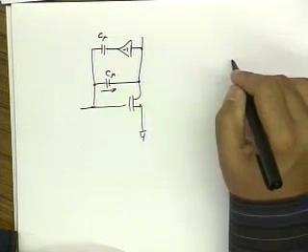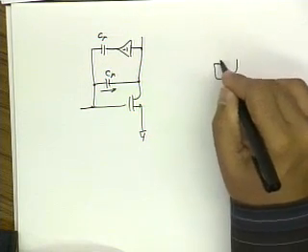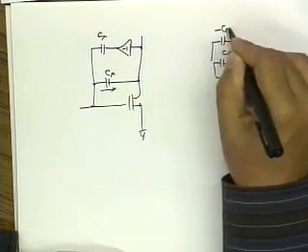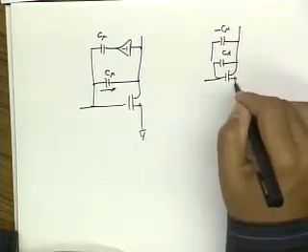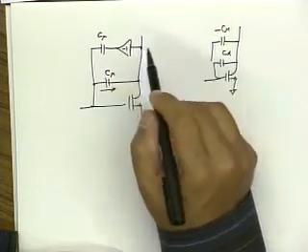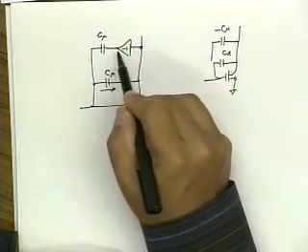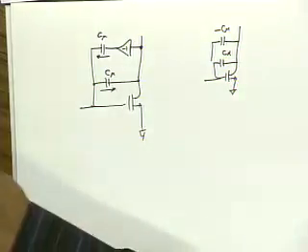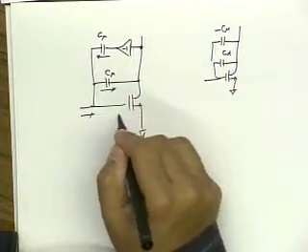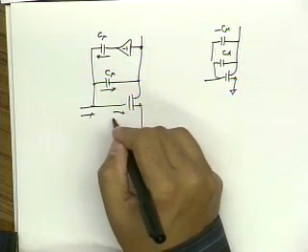That would be nice, if I could use a negative capacitor. C mu, and then minus C mu, and the currents would nicely cancel out. But I can't use a negative capacitor. The next best thing I can do is take this voltage, invert it, and produce a current that balances this current. So now the net current going in is just the gate current.